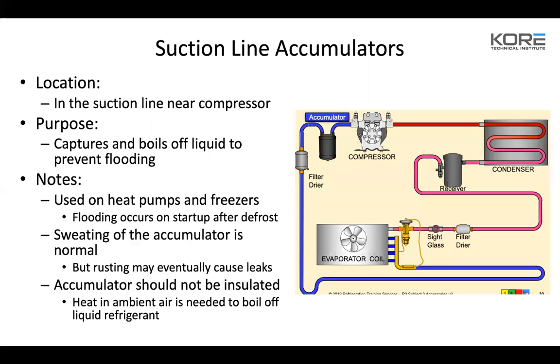Okay, and if we're flooding the coil, it's always good practice to try and get a condensing unit with an accumulator, because you're still going to get the superheat you need to your compressor, but you're not going to knock the oil out or flood that coil or flood that compressor. So when you're running that low of superheat, you're running flooded situations, you always want to see an accumulator. You're going to see accumulators on heat pump systems. You're going to see accumulators on large freezers.